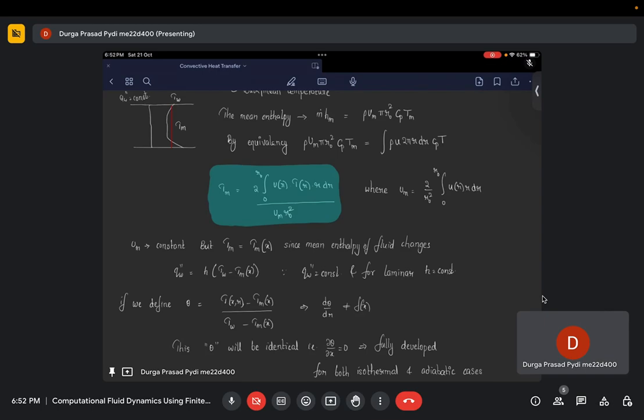Sir, actually, I want to find this graph. Is it correct, Nusselt? Because initially the value of Nusselt number decreases, and after developed flow, the value is constant, that is equal to 4.36. Yes, all of them are correct. The only thing that you have to update in the approach is to change the way you define your Nusselt number.